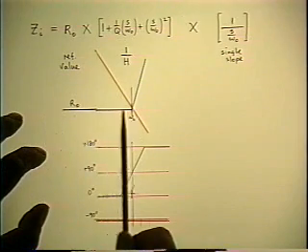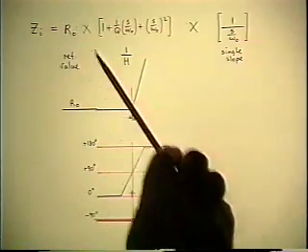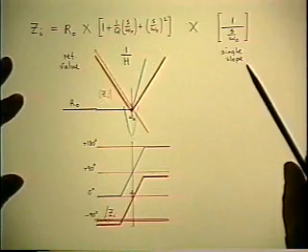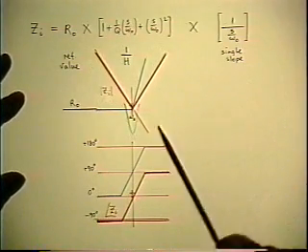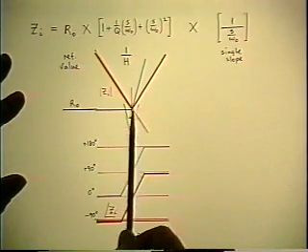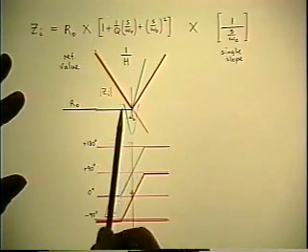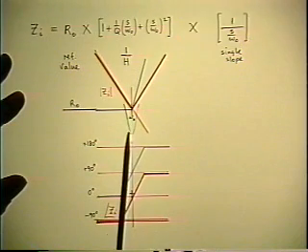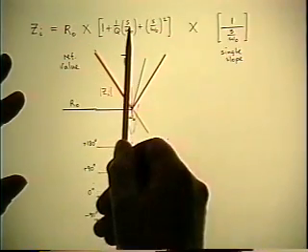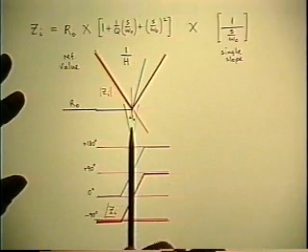So at this level, it will stay at R0, but I've got a negative slope to add to it, so the combination will follow the orange line, which is the negative slope, until the blue line goes up at a double slope, which cancels the single negative slope, so the result goes up on a single slope. And finally, I add back in the high Q peak, which is only relevant near the corner frequency of the filter, which I had in the first place, but I dropped it out while I was doing the intermediate construction. So now I can just put it back in now that I have the answer.